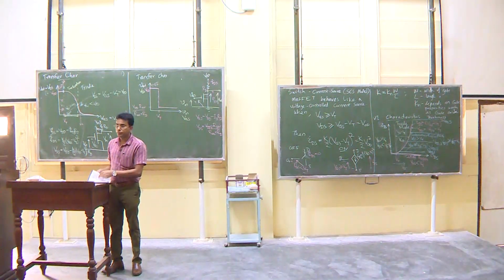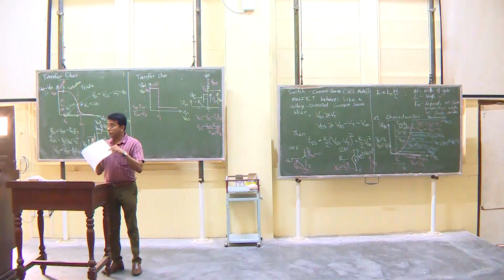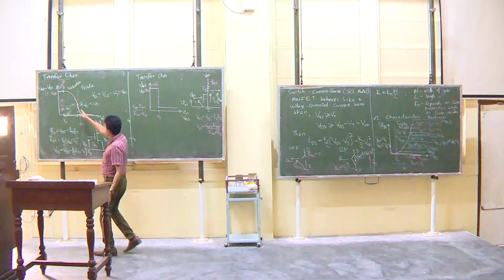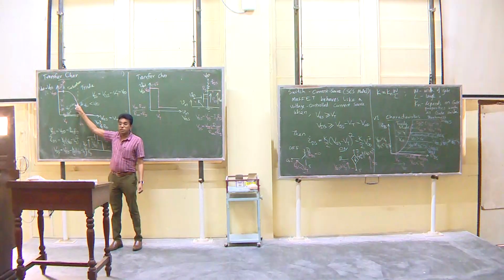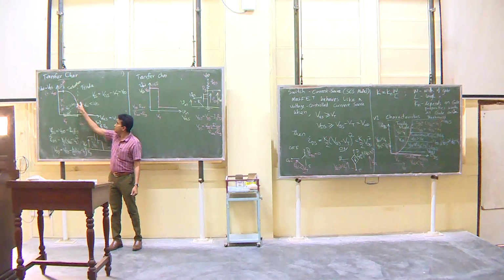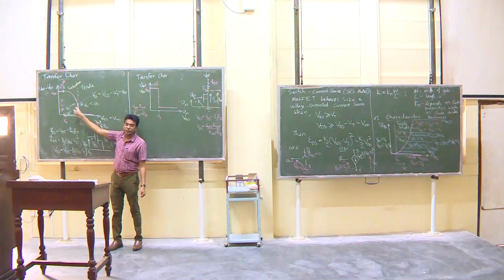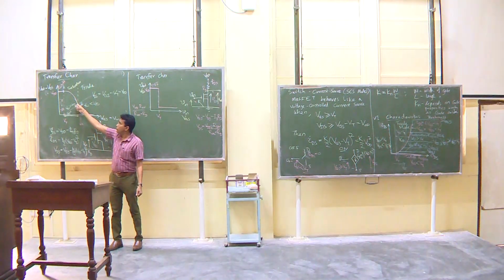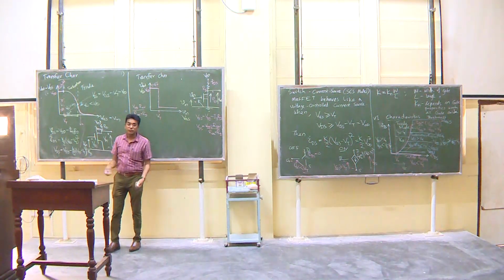Questions? The more important thing to remember is that this point occurs when VDS is equal to V overdrive, okay. So, that is the point beyond which it will not behave in the saturation regime.